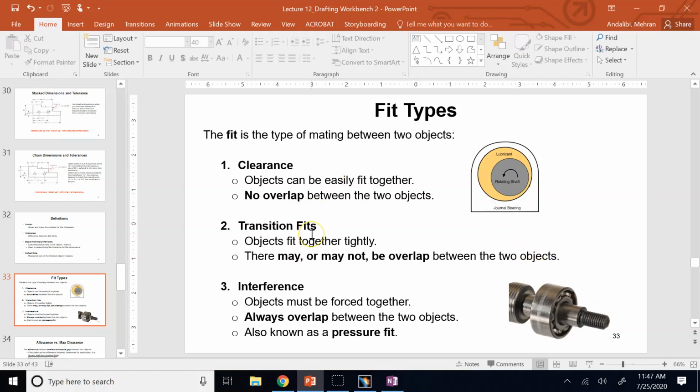And there is some fit in between that it's not super easy and the parts are not loose, easily going inside and out. And you don't really need to use a ton of force and heat to make it happen. But once the parts get inside, you need some moderate force to separate them, right? So it's not a snug fit, it's a relatively good fit.